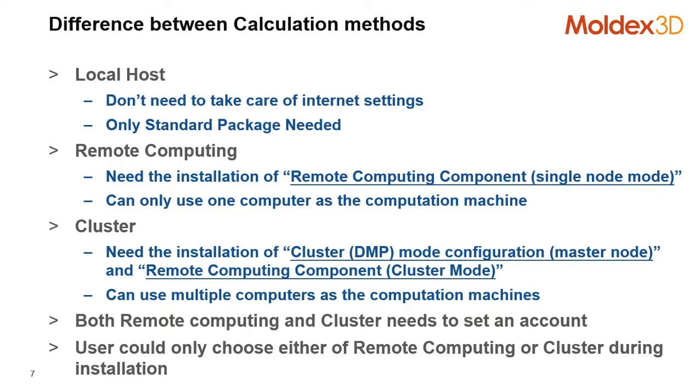The last one is the cluster. Cluster mode, you need to install the cluster mode configuration and the remote computing component in each single computer that you would like to use as the computing node. So make sure you make the installation on each computer that you would like to use, and then you could use all these computers as the computation machines, so you can increase the calculation speed quite a lot.